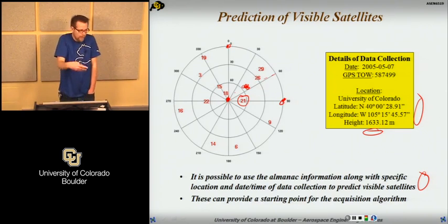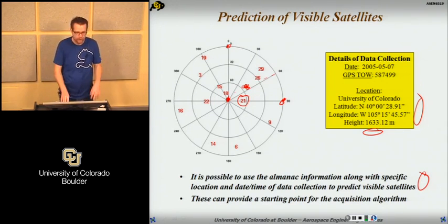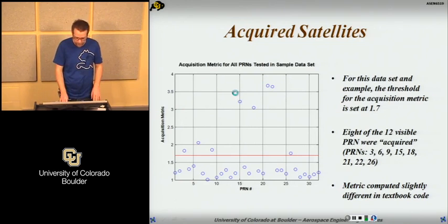But of course, if we can compute that, then we can also compute what we expect the Doppler to be just from the satellite moving relative to us. All right? You also have user Doppler, but it's typically much, much smaller. So if you're a car on a highway, that doesn't move very fast compared to the GPS satellites, right? What does mess it up a little bit is if you accelerate. It actually does come into play, but now I'm getting too far ahead again.